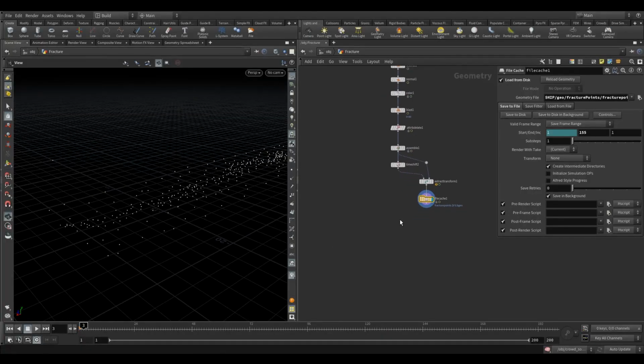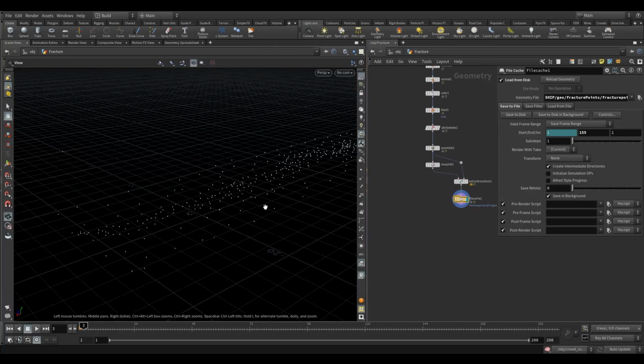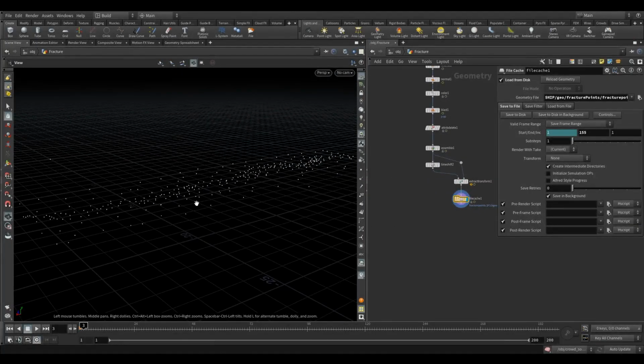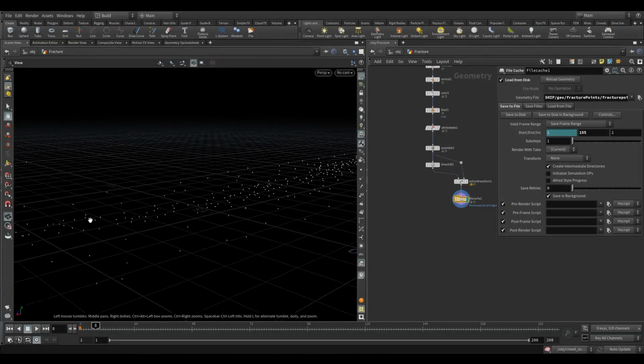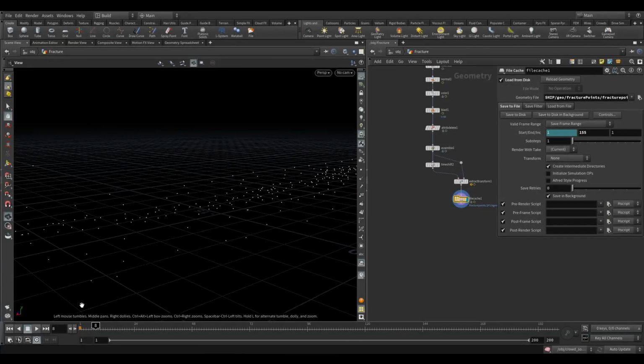Great, and so I want to use these as a collider for my simulation, right? So if I go through each frame, I obviously get one jump per frame. Now when I go into my simulation, I'm going to have sub-steps. So between each frame, there's going to be calculations happening on the position of my agents between each frame, and with these jumping per frame and not with sub-steps, we'll get weird kind of explosions. Maybe I'll show you later with this turned off.